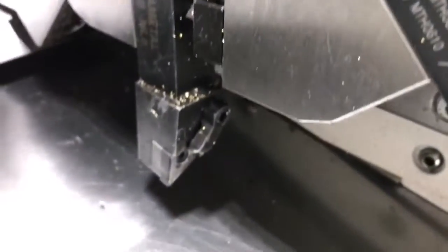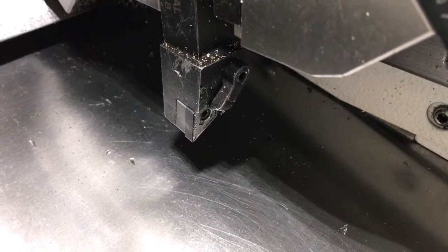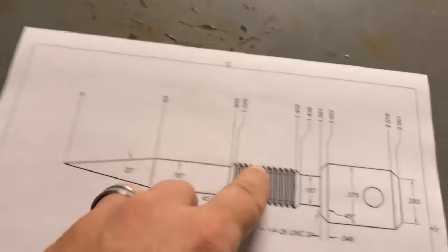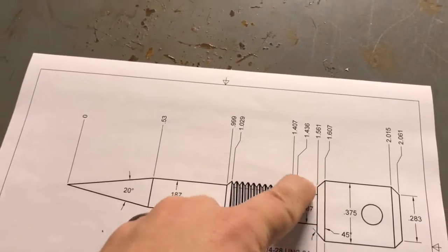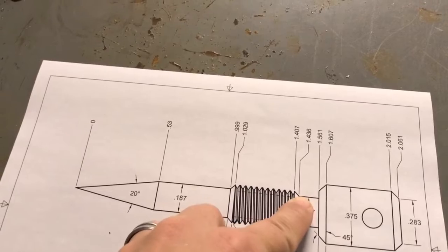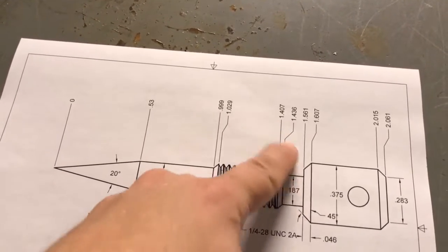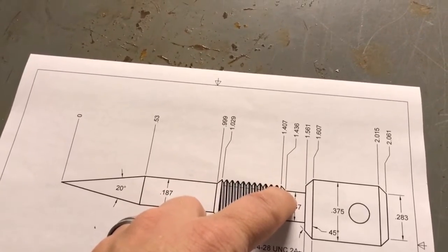Tool 2 has a shallower angle there, so it's not quite as steep of an angle. Tool 2 will not get into here as good as tool 8 will. Tool 8 will pretty much be able to rough this out and give me a usable relief here. I could come back in and do a groove here if I needed to, but I shouldn't really need it with that tool number 8 there.